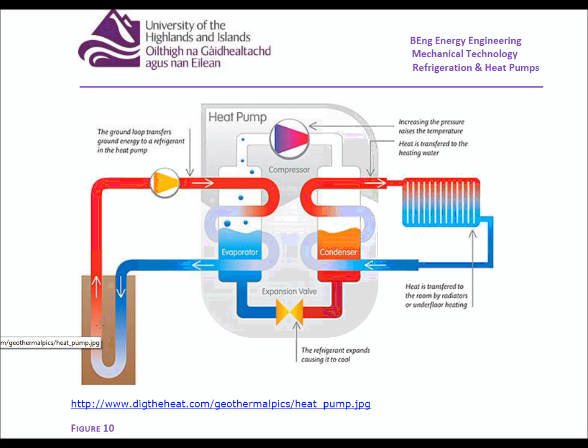So it's all about weighing up, when you're designing the system, the running conditions, the actual demands on the heating system, the ground conditions, and so on. All these things will be taken into account in designing one of these systems, as well as obviously thinking about the rate at which heat is being removed from the actual secondary ground source.